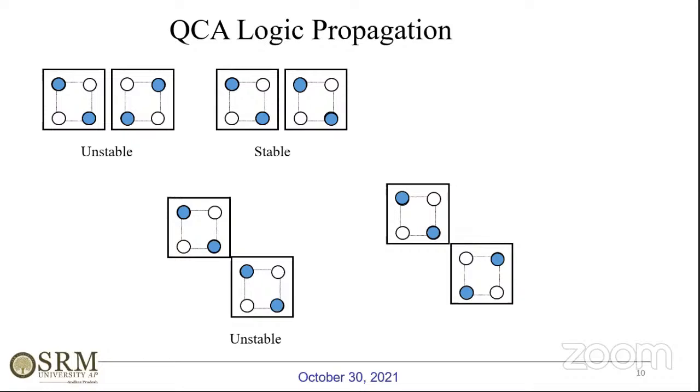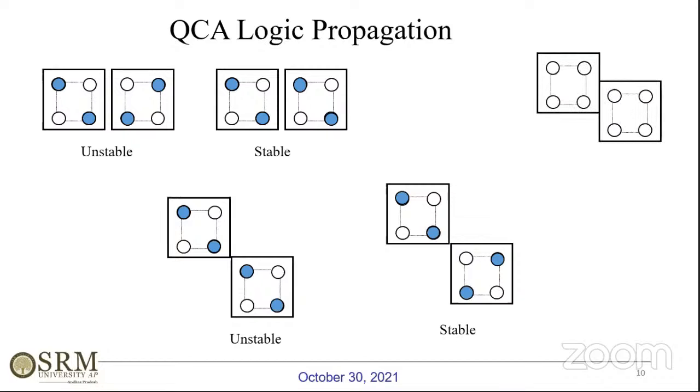So this is considered a stable state. Then it is one of the NOT gate operations. In NOT gate operation, there is one more example, the offset NOT gate operation. That is the offset cell. When we connect two cells like this, normally the QCA cell is 18 nanometer in size. When we give one cell and another cell, we translate by 9 nanometer, and it works like this. This architecture also works as a NOT gate operation. So this is also one type of stable state.